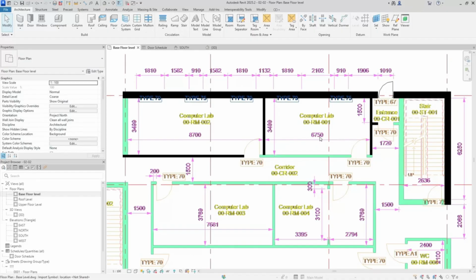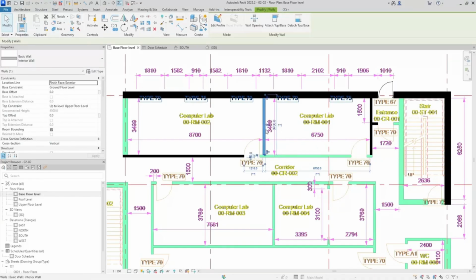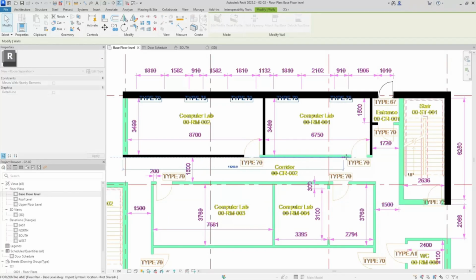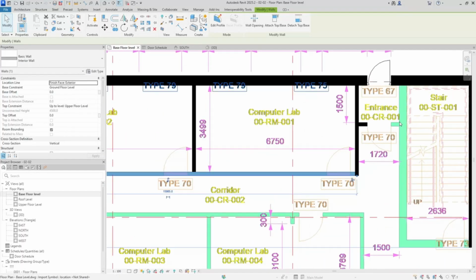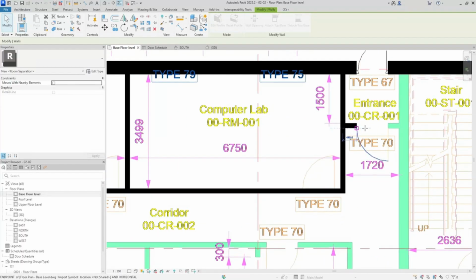Again, selecting the walls in Plan View reveals the dynamic grips at the wall ends, and by dragging these you can control where the wall starts and ends. And again, you may need to zoom in for the best results.